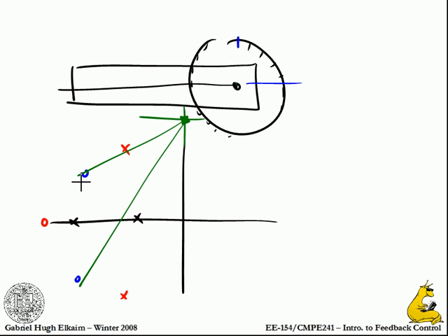All right? Then you would rotate down to the first pole. You would stick your finger on the center again, so nothing rotates. Rotate it down to the first pole. Pin the wheel. Go back up to horizontal. Do it for the next, for all the poles, all the zeros, and then look at it and read off the phase. All right? It doesn't take very long to get actually very fast at this. You have to solve for the poles and zeros and then draw it really accurately first. Well, you just draw it to scale.